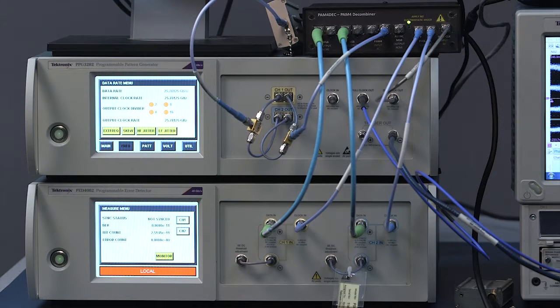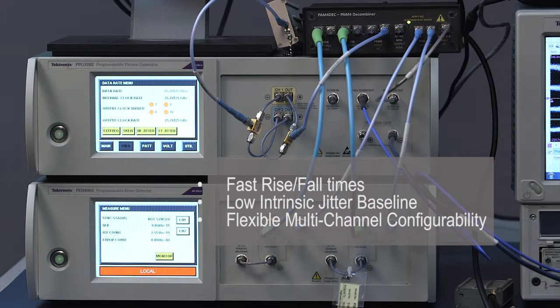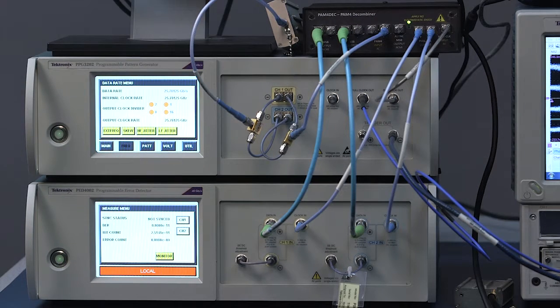This pattern generator is the ideal tool for PAM4 signal generation because of its very fast rise-fall times, low intrinsic jitter baseline, and flexible multi-channel configurability. The intrinsic random jitter, or RJ, of the PPG 3202 is less than 250 femtoseconds at 32 gigabaud, and the edge rates, or rise-fall times, are 11 picoseconds.